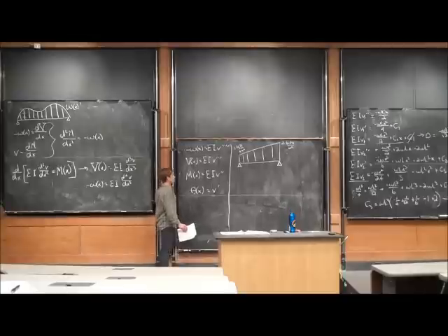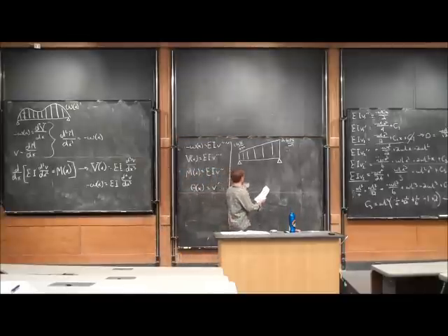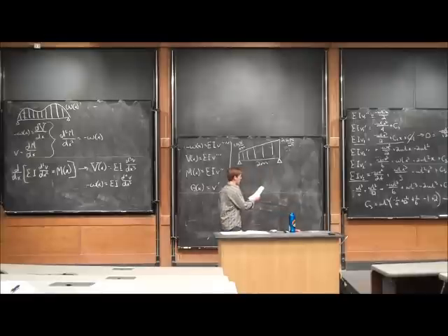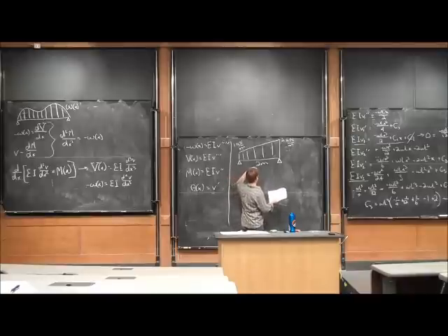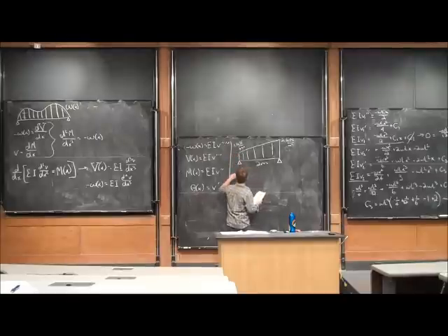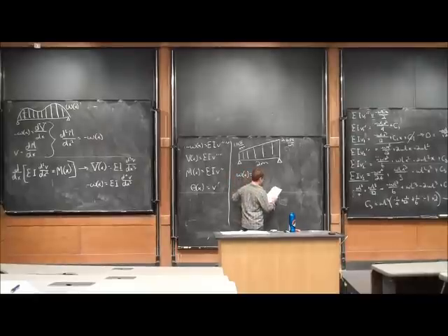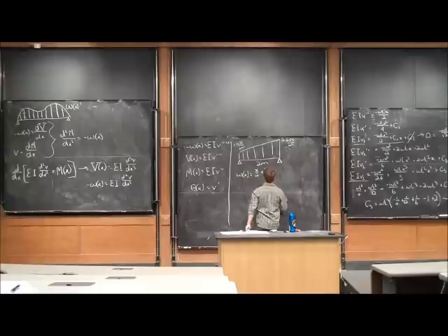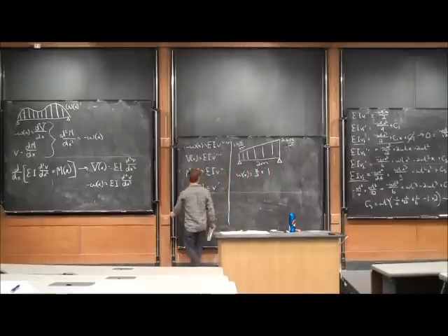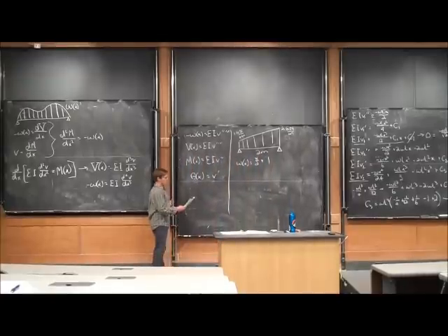We know it increases from 1 to 2 over, let's say that this length is 2 meters. So based on this, we know that it increases from 1 to 2 over a distance of 2 meters. So my rise over my run is going to be 1 over 2 in this case, and it starts at a constant value of 1. So our loading function is going to be equal to x over 2 plus 1. That is the loading that we see on the beam.